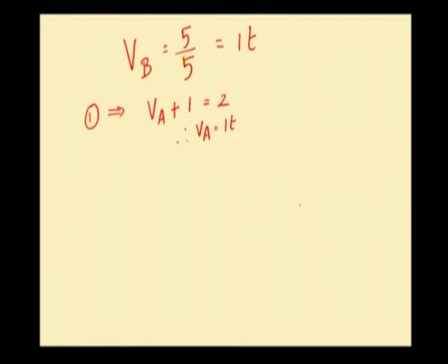Now, let us consider the free body of joint A. This is joint A. At joint A, you have vertical reaction component VA, magnitude of VA is 1 ton. Then you have the horizontal member AB, and you have an inclined member which is AC. Let us indicate the force in the member AB as FAB and force in the member AC as FAC. Our aim is to determine the force in the member FAC as well as force in the member FAB. The inclination between these two members is also given, which is 45 degree.